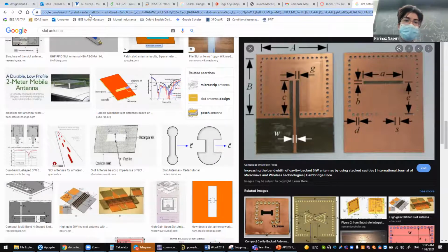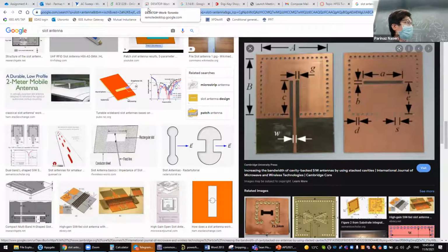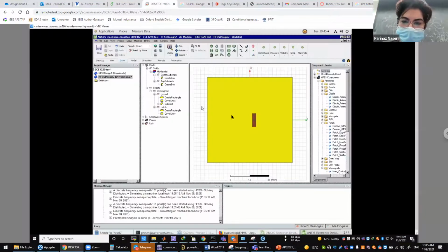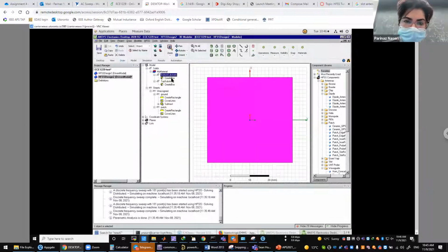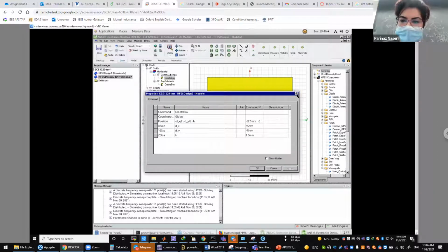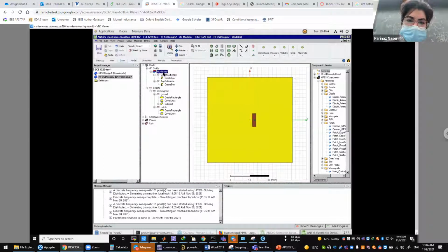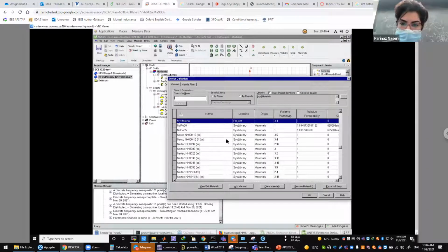So now we want to calculate this microstrip line. We want to see what should be the width of this microstrip line. I'm going to go back here because I forgot what the material was. The thickness was, I think, 1.5 millimeter, and the permittivity you can always go back here, properties, look at it. My material, I said 3.4.